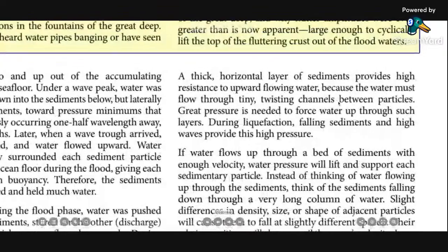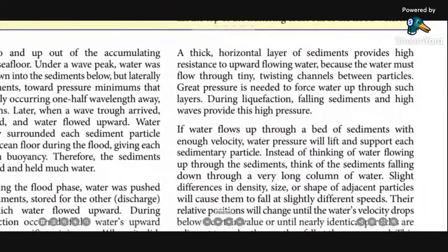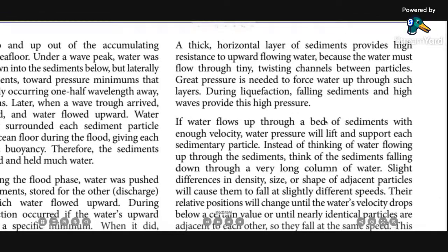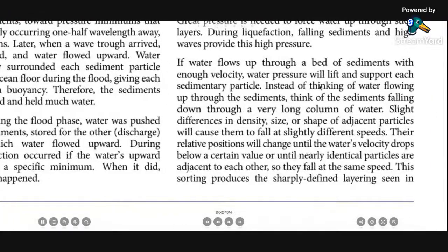A thick horizontal layer of sediment provides high resistance to upward flowing water because the water must flow through tiny twisting channels between particles. Great pressure is needed to force water up through such layers. During liquefaction, falling sediments and high waves provide this high pressure. If water flows up through a bed of sediment with enough velocity, water pressure will lift and support each sedimentary particle. Instead of thinking of water flowing up through the sediments, think of the sediments falling down through a very